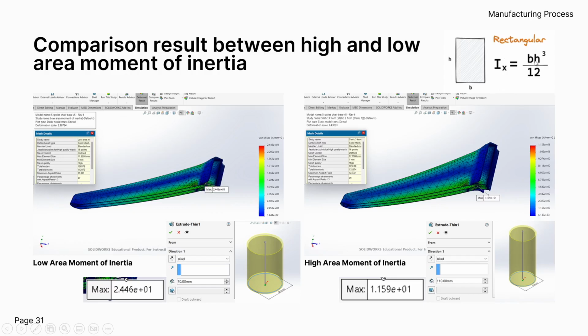But h affects more, h to the power of 3. So by increasing h just by a little bit, it is already to the power of 3 times the amount of b, your base here. So you can keep this part thin, and the height just make it tall, so that you can create a higher moment of inertia and better structural integrity.